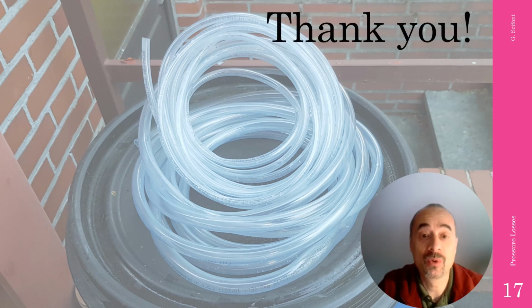The presentation wanted to demonstrate the use of the formulas for the calculation of the water flow, knowing the head, or vice versa, under consideration of the pressure losses, and we learned how they are built. In the examples, we have introduced a friction coefficient that takes into consideration both the distributed and the concentrated losses. For a more complex network, it is in general not possible to adopt an overall coefficient, but the procedure is similar.